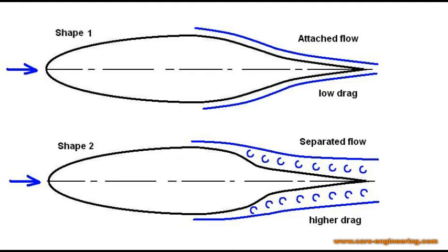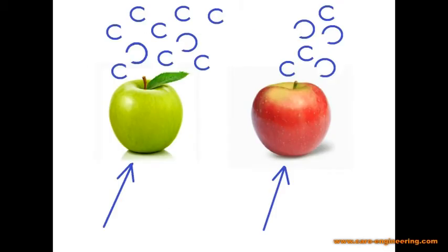The skin friction drag is also a function of the Reynolds number. The Reynolds number is the ratio between the airspeed times the length divided by the kinematic viscosity of the air. The latter can be regarded as constant, so only speed and length are the variables. For two objects of different size and speeds, the flow is similar if the Reynolds number is the same, so this number is important for making sure you are comparing apples to apples.